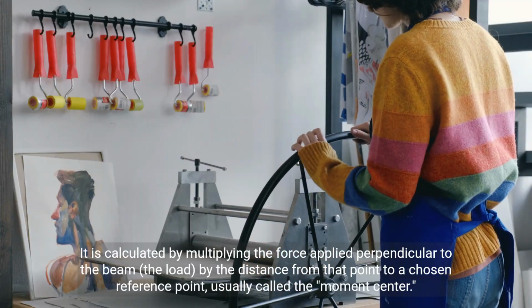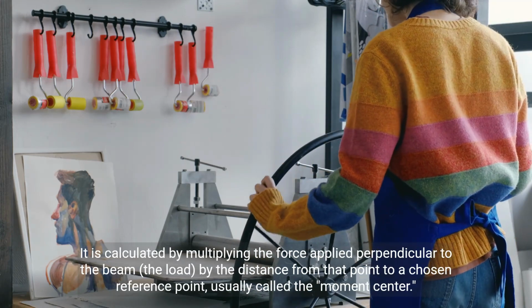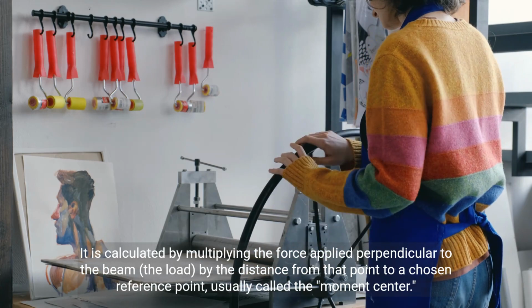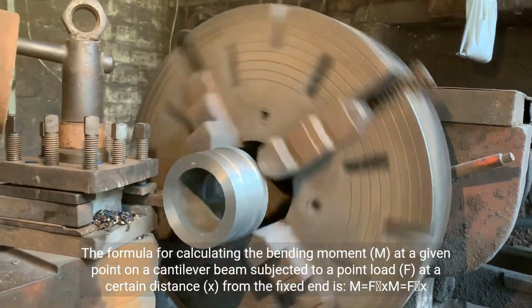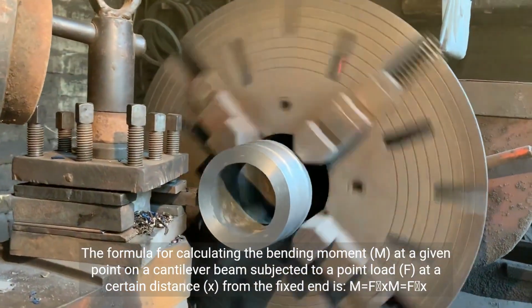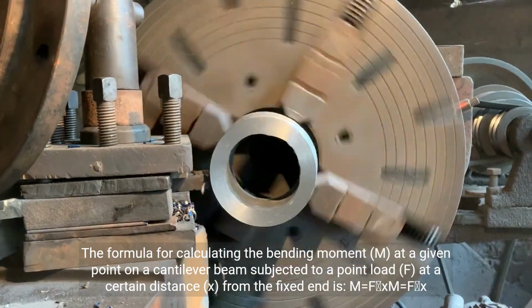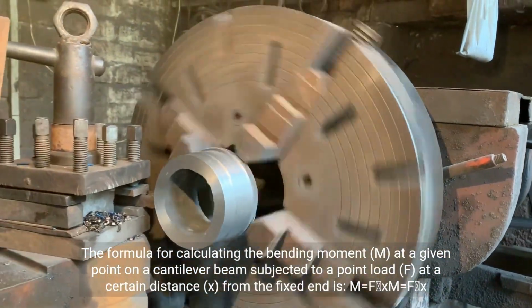It is calculated by multiplying the force applied perpendicular to the beam, the load, by the distance from that point to a chosen reference point, usually called the moment center. The formula for calculating the bending moment, M, at a given point on a cantilever beam subjected to a point load, F, at a certain distance, x, from the fixed end is M = Fx.